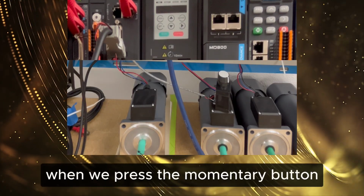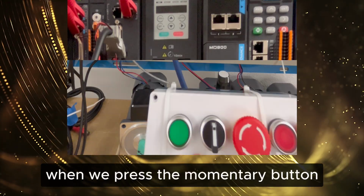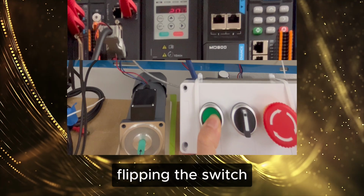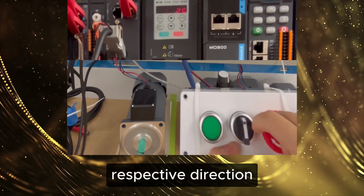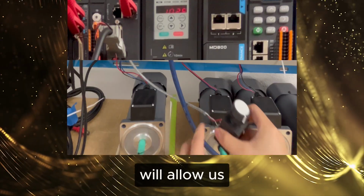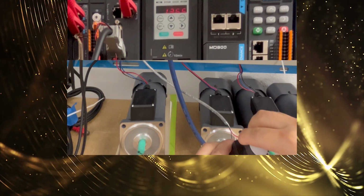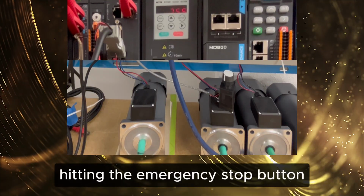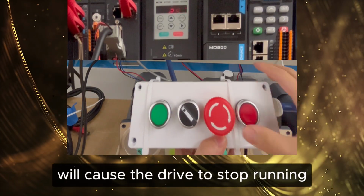As you can see, when we press the momentary button, the motor will jog forward at a rate of 2 Hz. Flipping the switch will cause the drive to run in each respective direction, and adjusting the potentiometer will allow us to control the drive's running speed. Finally, and most importantly, hitting the emergency stop button will cause the drive to stop running.